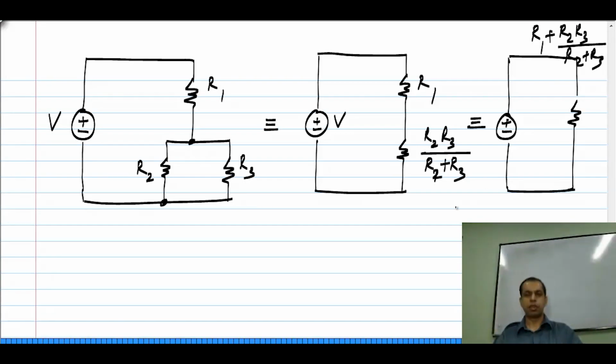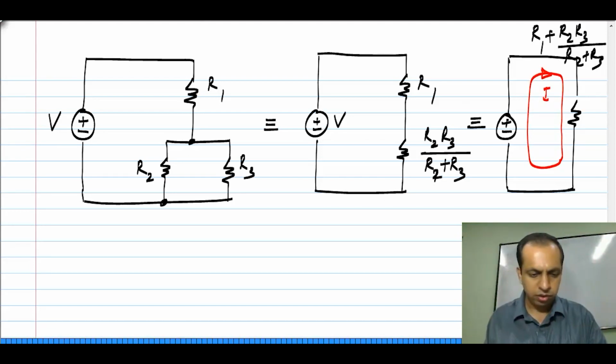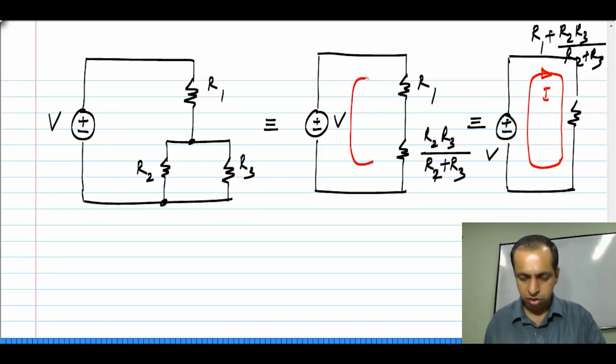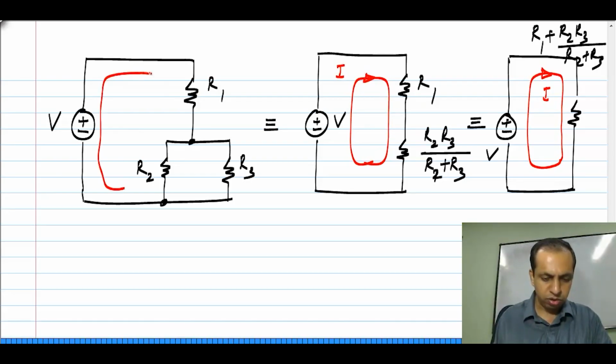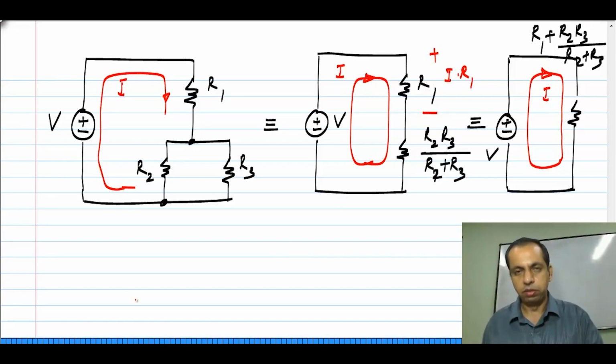Okay. So, now you can calculate everything from this, that is, first of all, you can calculate the current I, right. So, this is the voltage V, of course. I will be this V divided by the total resistance, and the same I will be here and also here. Okay. And if you want to calculate the voltage across R1, it will be I times R1, which you can easily calculate.